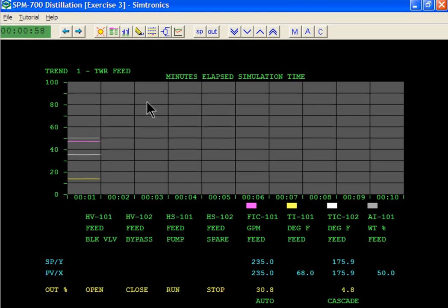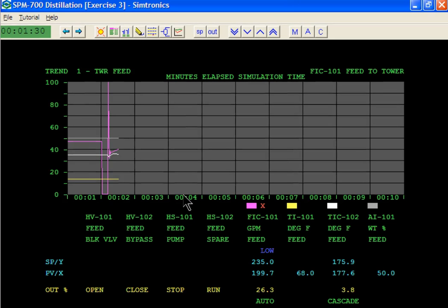Normally, between 1 to 2 minutes into the simulation, a pump, or a temperature sensor, or some other indicator or controller, will fail. The failure may be sudden, or in stages, just like real equipment. The point of the exercise is for the operator to recognize the problem and take corrective action to minimize the damage or cost. Responding to alarms will be covered in detail later in this tutorial.